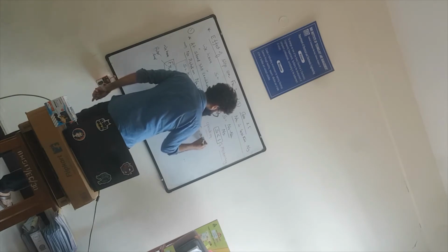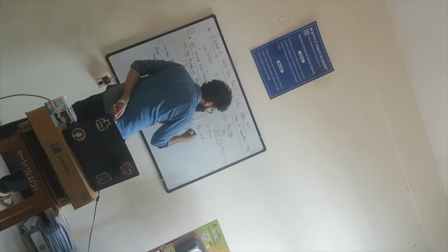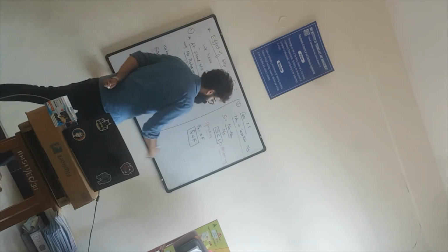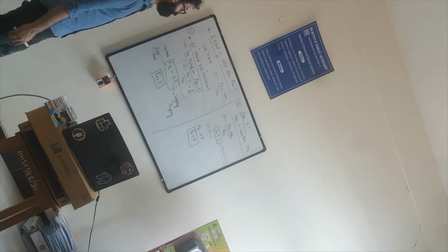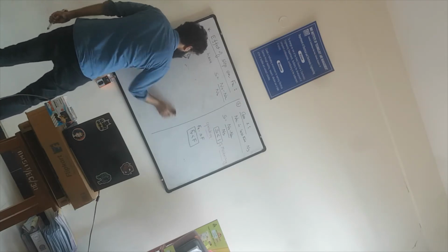Once again, let us write the frequency expression: Fr is slip times F. So slip is less than unity, due to which Fr is always less than F. Okay. So the frequency of the rotor induced EMF is always less compared to the frequency of supply. And this condition you will get only for motoring operation. Alright. So that's your second case. Okay. Now let us consider the third case.